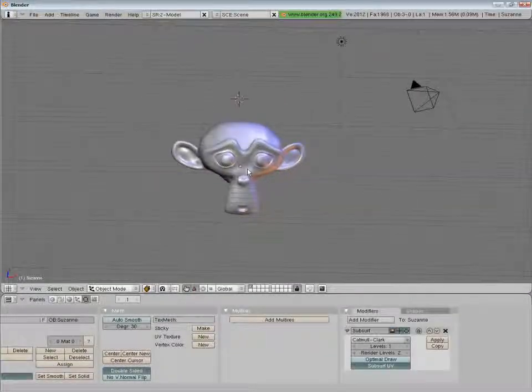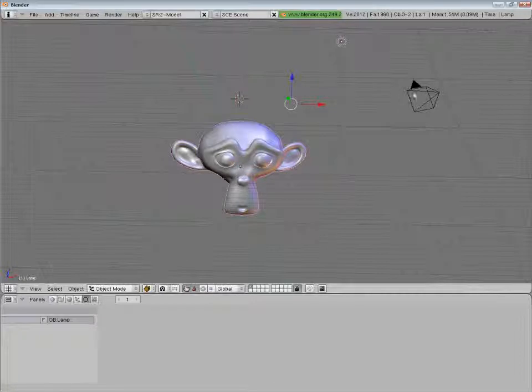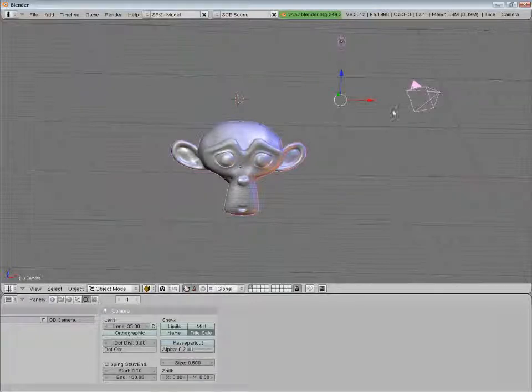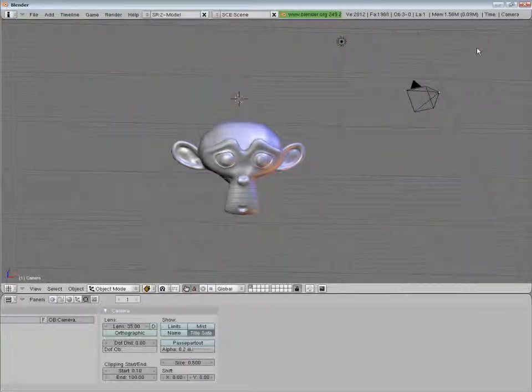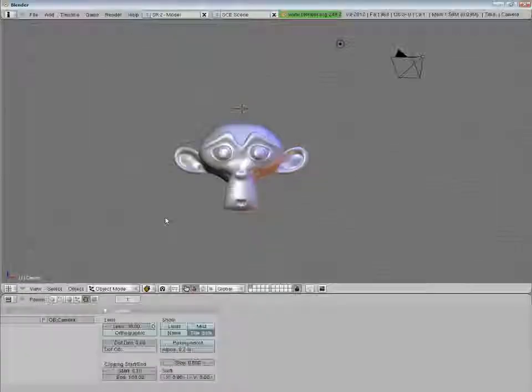To select anything in Blender, we use right click. To select multiple objects, hold shift and then right click on the objects. To drag select, press B. To select all, press A, and to deselect, press A again. Let's start with adding objects.